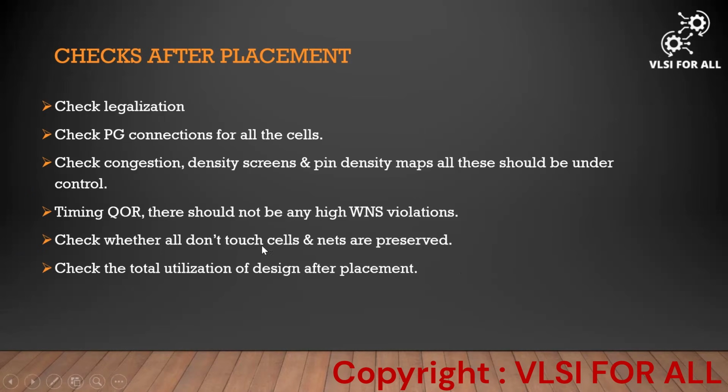And check whether all don't touch cells and nets are preserved. So in the placement stage, the synthesis team itself provides some don't touch cells or don't touch nets by default. Whether these are preserved or not, whether they are being used or not, we have to check that also. If any don't touch cell is coming into the timing path, we have to check whether it has don't touch cells or nets accordingly.